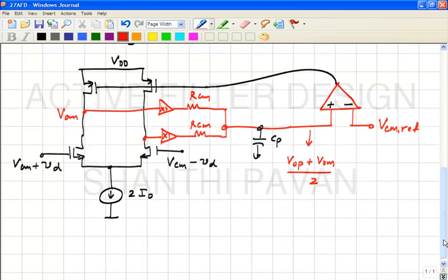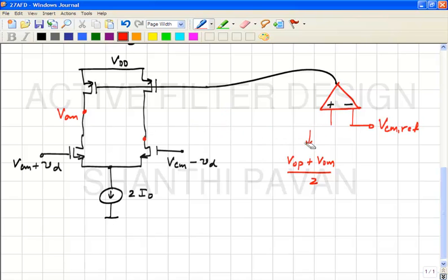All right. If you want to build these voltage controlled voltage sources using transistors, what is the simplest transistor based voltage controlled voltage source that you know? The source follower, the common drain amplifier. So what we will do is replace this detector with something based on a